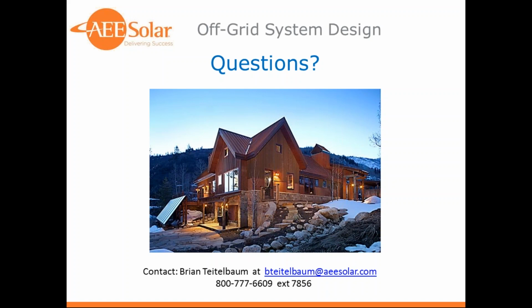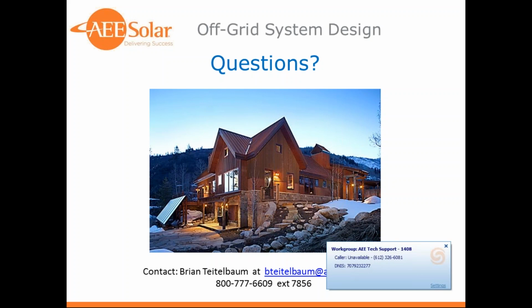There are even separate standalone modules that can be used to automatically start generators. Now the thing is, the generator has to be set up for remote starting. If it's the type of generator where you have to go out and switch it on, you have to pull a cord, that's not a remote start generator. So you're going to have to do that manually.